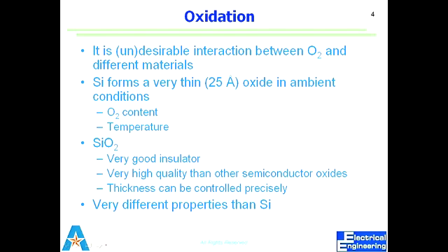So in this course we'll use 44, but you'll see the number is 42 somewhere, say 46. It depends on the orientation of silicon and many other factors. But we take 44 as a standard number in this course. So even if we don't do any special processing like high temperature or humid environment, silicon always forms an oxide layer, which is called native oxide.